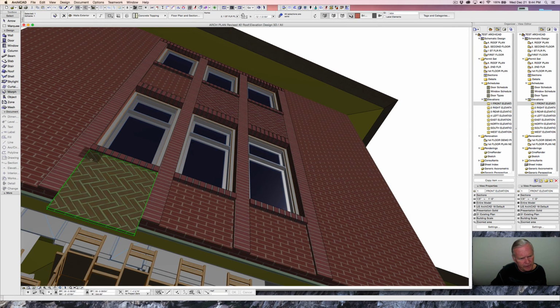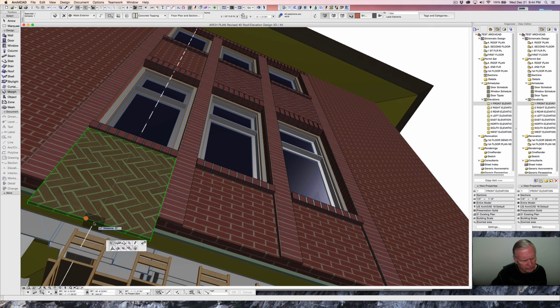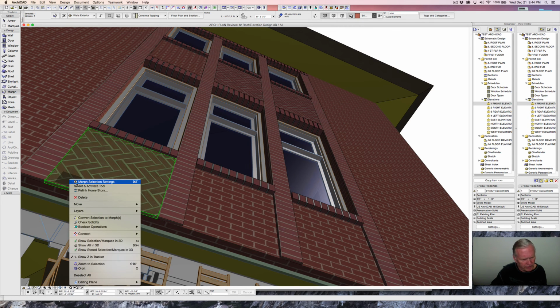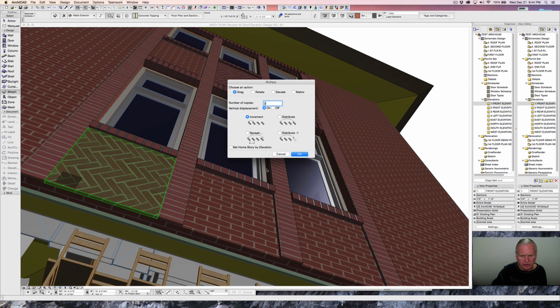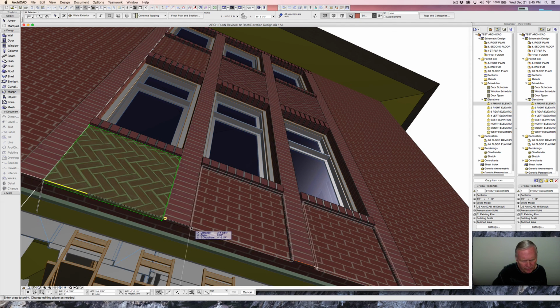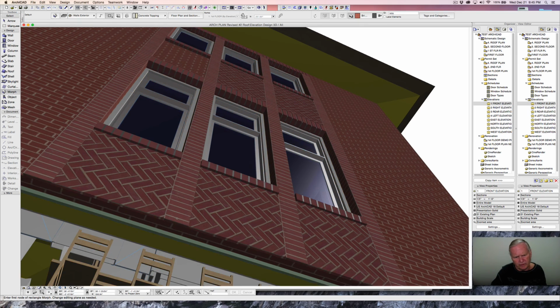All right, and then we'll go in a little bit so we can get that icon to change. Pull it into there like so, and do a right click on that, do move, multiply. We're already set correctly for 2, say OK, and we're going to grab that point there, bring it over to here, and we've got those 2 set twice, and we're in.